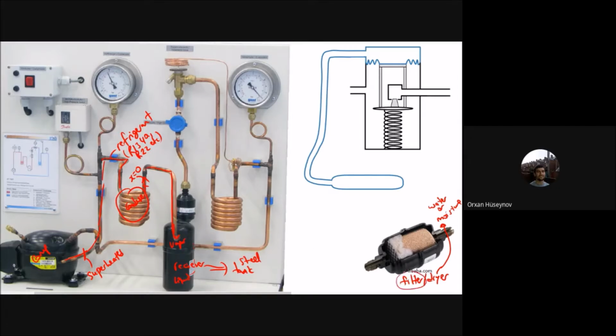This filter part is used to filter the particulates that are larger in size, and you are preventing them from moving inside this tube system. At this part, you can see what is called the desiccant. This is not as simple as I'm saying it. The filter and dryer has different components, and different reactions happening inside this system. This desiccant prevents the moisture, and then you have the screen here. You can see that screen, and you have a grill system here. This grill system prevents the particulates from entering this refrigeration system.